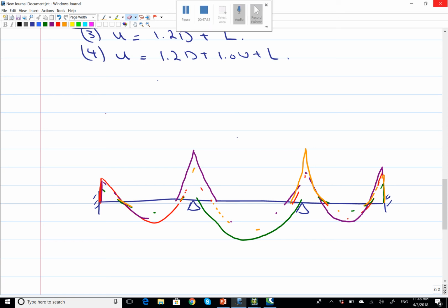As you see here, at this specific point, for example, there are two bending moments, a positive one and a negative one. Why is this? Because this is the envelope. It comes from many load cases, not just one load case. So how do we make the STAAD software draw this envelope for you? This is what you're required to find in your project: the envelope for all the load cases that you're going to model. So how to do this?